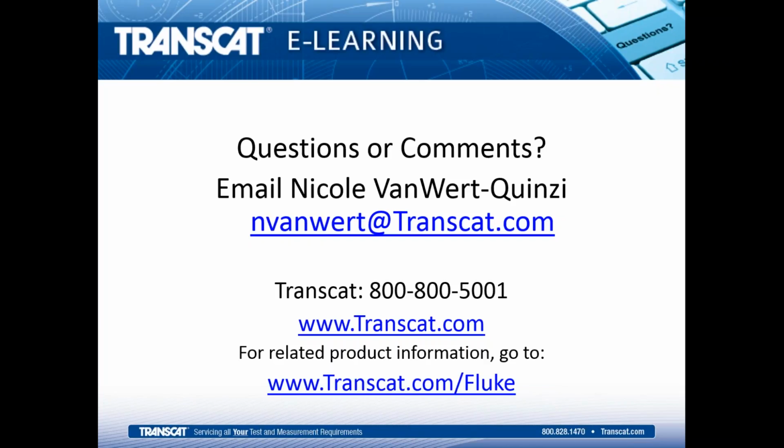So yes, you can. Now the question about doing the surface sensor calibration on the dry block. Well, as we've talked about earlier, there's this thing called axial uniformity, and so there's a difference between the temperature at the bottom and the temperature at the top, and the calibrated sensor is all the way down at the bottom. And so while some folks might suggest that you can do the calibration by surface calibration with a dry block, I don't think I would recommend it. There's some large uncertainties there. We do have a surface calibrator specifically designed for doing that.